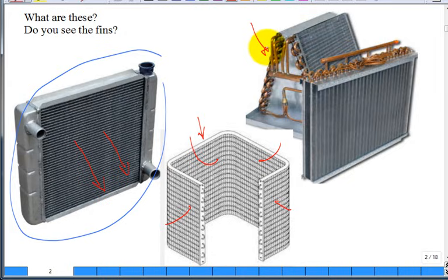And over the outside of the coils, what's happening? Air's coming up and then going across like that and across like that in the duct system. And so it's air on the outside. This would be a flat coil, evaporator coil. Not all evaporator coils are A coils. Most of them, or a lot of them are, but they're different shapes and geometries.